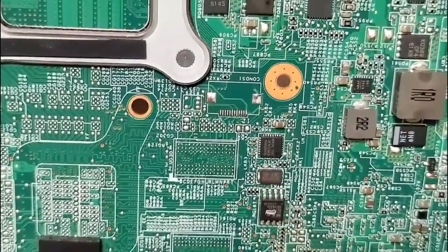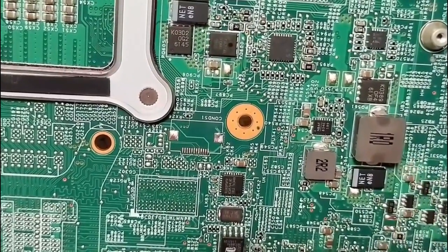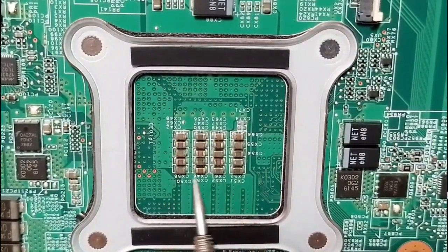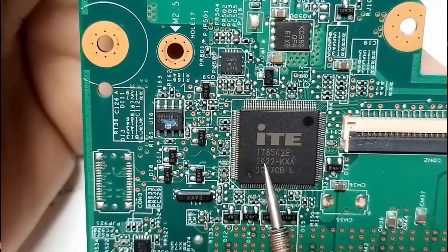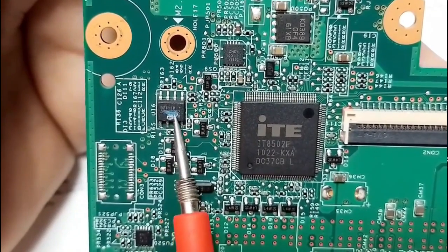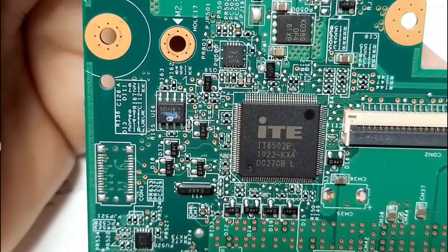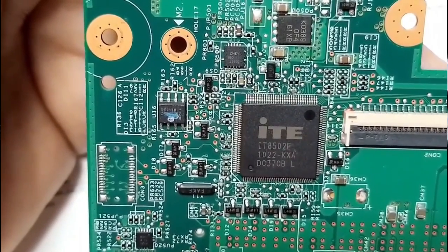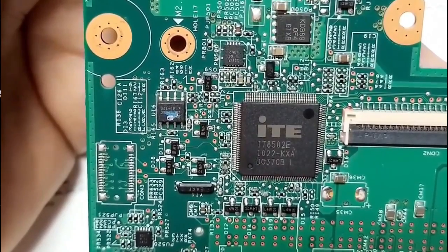Crystal oscillator, IC. So tantalum capacitor, inductors, MOSFET. Here also we have MOSFETs. This is basically ceramic capacitors. On the backside of the CPU, this is the super IO, the super input-output IC. And here we have another BIOS chip, with this mark, as you can see. Usually you will find just one BIOS chip in laptop motherboards, but sometimes you can find 2, like this motherboard.